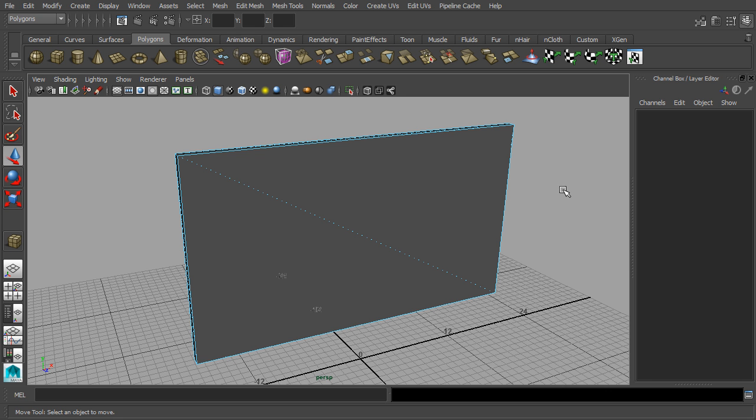Maya dynamically triangulates these polygons or flat planar surfaces as you work. And you don't need to think about the triangles. That just sort of happens behind the scenes. The triangle is the basic atomic unit of a surface because a triangle is always flat. Quadrilaterals, however, can be bent. They should be flat, but it's possible for them to be bent. And whenever they're not coplanar, it's a good idea to chop them up into explicit triangles so that whatever renderer you're working with is going to understand that topology. So it'll draw it correctly. So if you've got non-planar faces or non-planar polygons, you should chop it up into triangles.